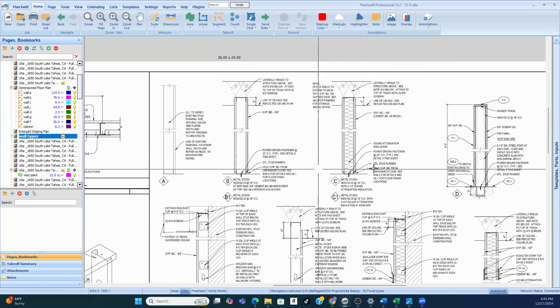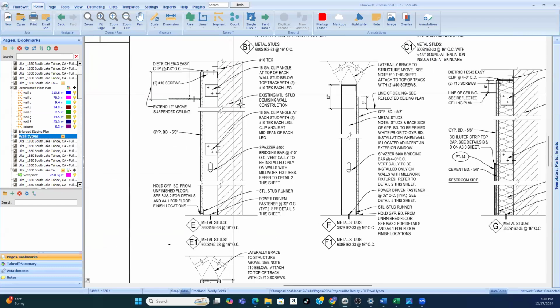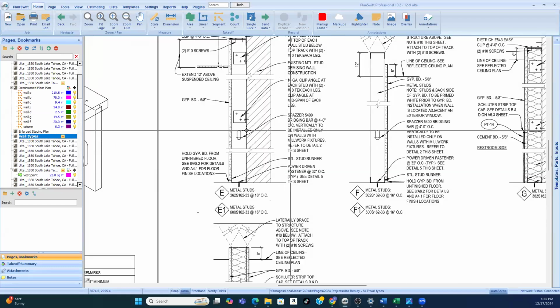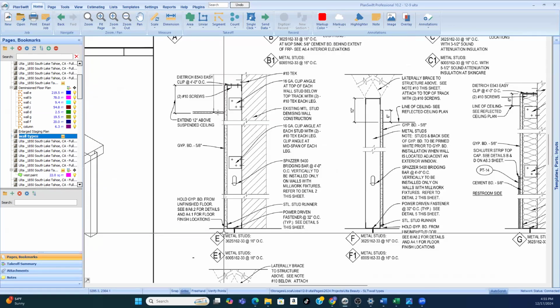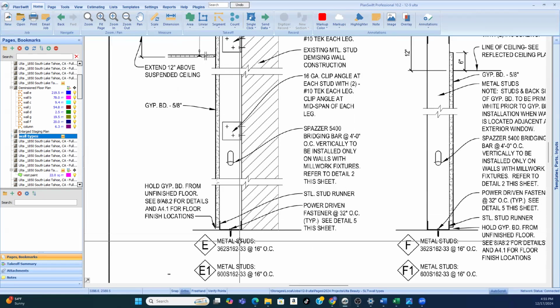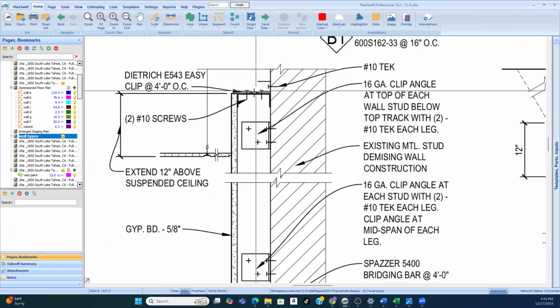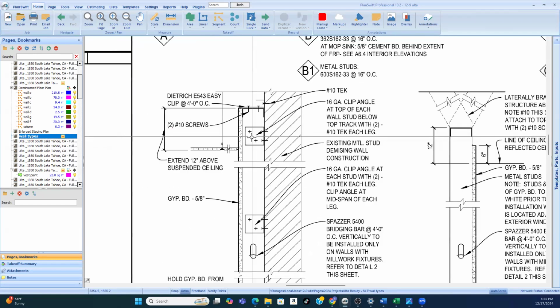And so when we're looking at the wall legend, we had a lot of wall E, which was the exterior, because that's the exterior wall. And so it's going to really point out, whether it's the roofer, the insulation, whoever, you use these section views to build your material quantities because it points out exactly everything that you need, from the runners to how high up the drywall is going to go, the top and bottom runners and any of the additional supports and stuff.